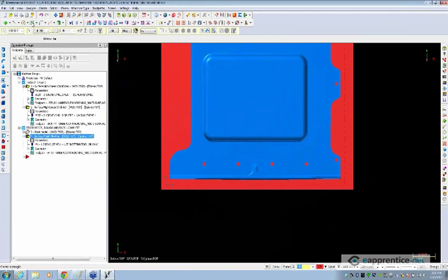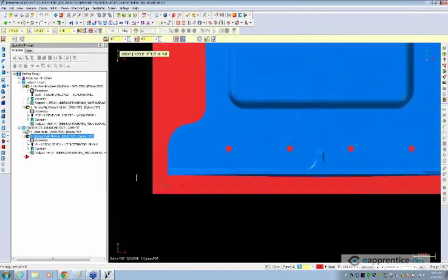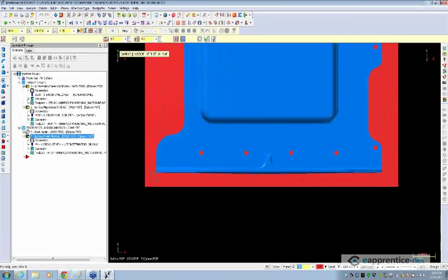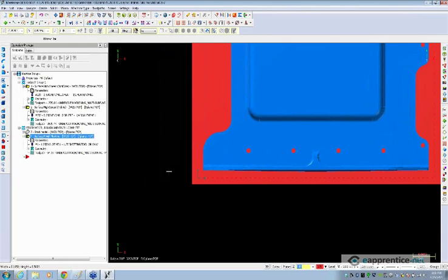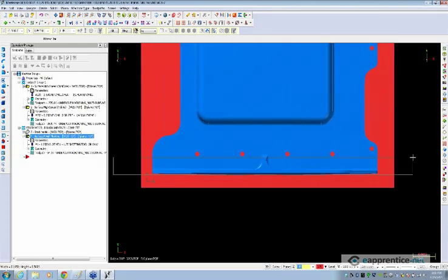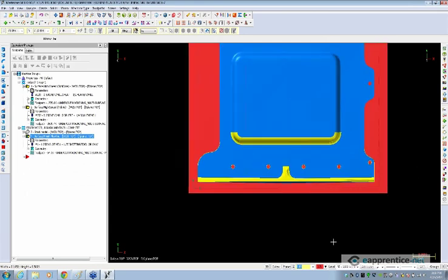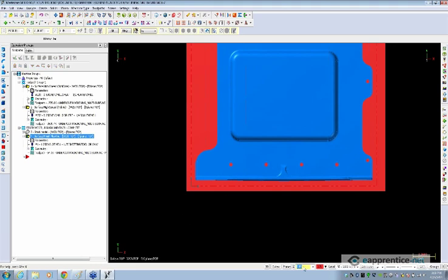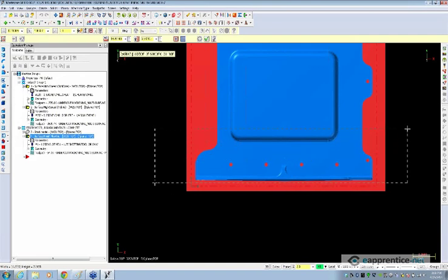And what I'll do is just create a rectangle. And I want to make sure that the bottom edge of my rectangle is just beyond the edge of these surfaces here. Go over here. So now I'm basically telling Mastercam, oh, let me do that as create rectangle, that'll help. So let's go Z depth, 2 inches, and let's create a rectangle. And turn off surface, there we go.